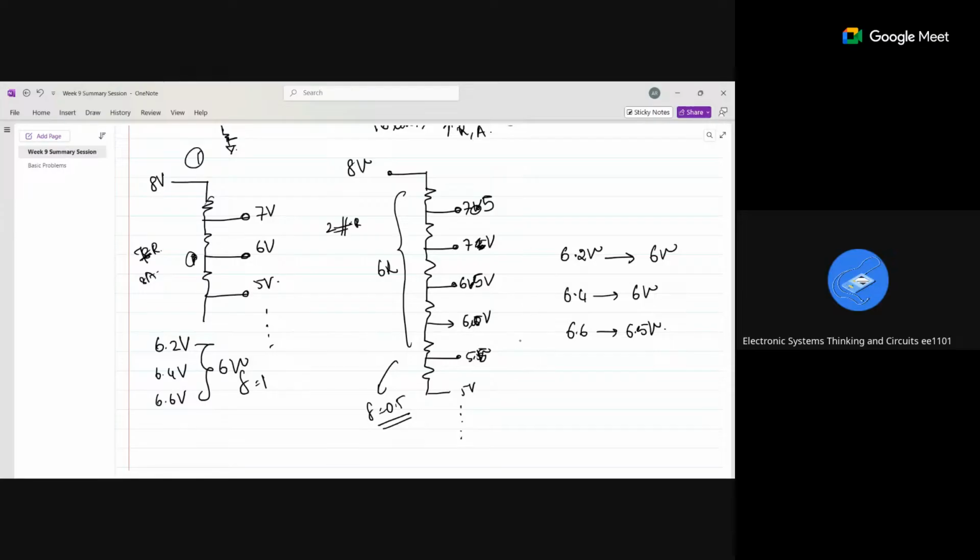So if I want to measure 0.2 microvolts, this is 5 volts, here it is 1 volt. If I want a delta value such that it is 0.2 microvolts, imagine the number of resistors and amplifiers that I have to use. It will be in thousands, very high. So that's the reason we don't go for flash ADC when you want to measure microvolts and all.